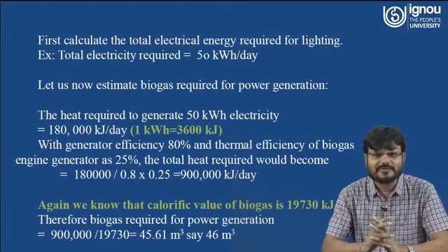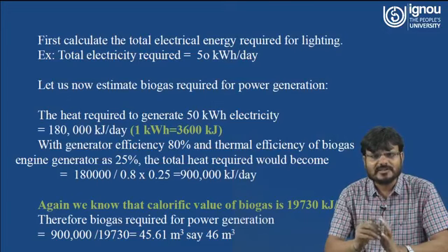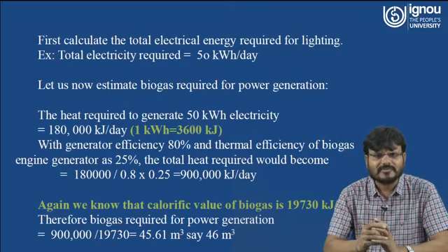Here I am assuming that the generator efficiency is 80% and the thermal efficiency of the biogas engine generator is 25%. So the total heat required will come to around 900,000 kilojoules per day. Now we know that the calorific value of biogas is 19,730 kilojoules per cubic meter.